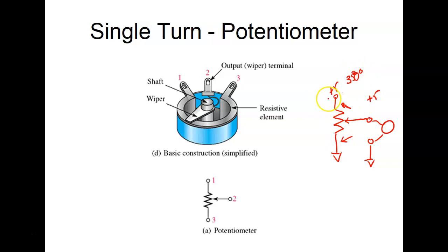And I place 5 volts on that. Then how many volts could we get per degree? Up here, we have a 350 degree pot, and I've got 5 volts attached to the top. What would be our volts per degree?